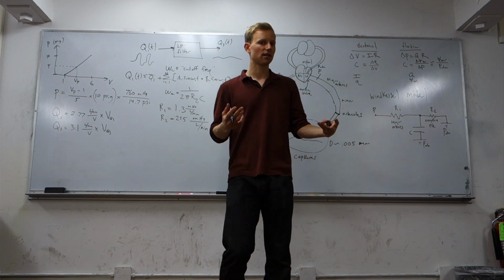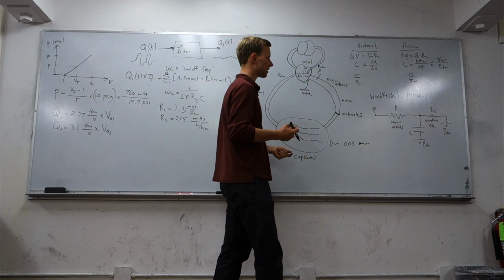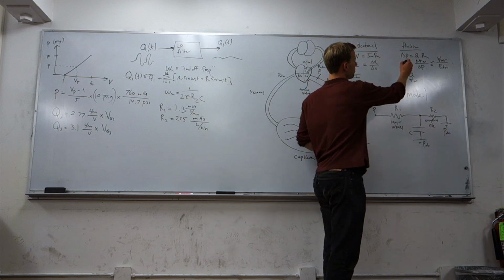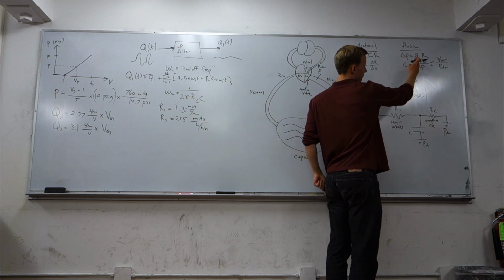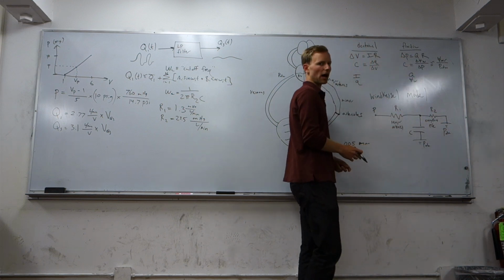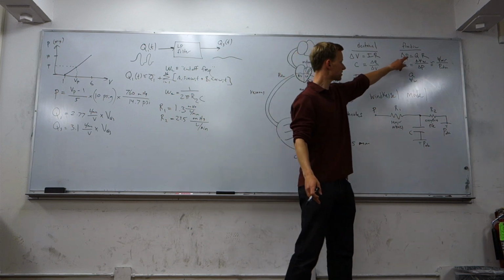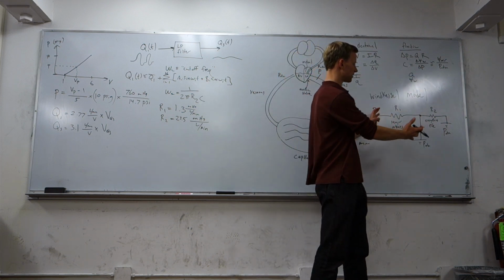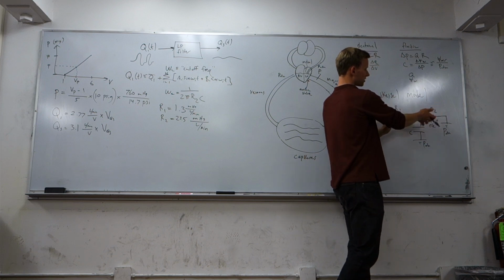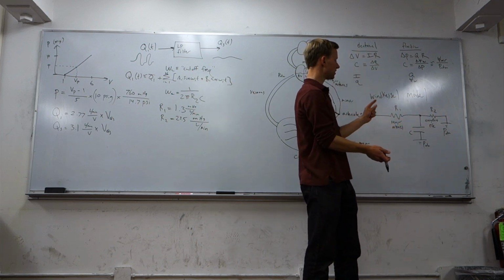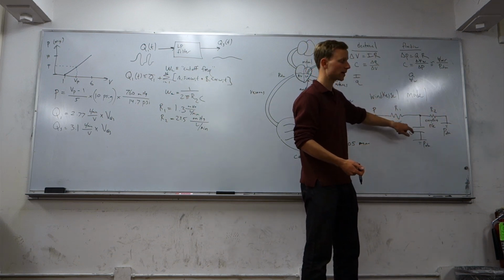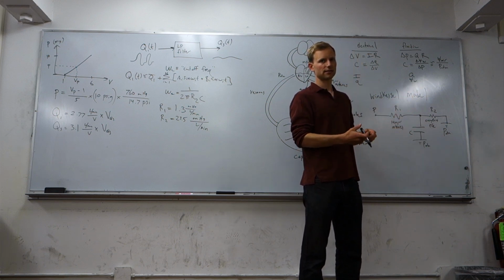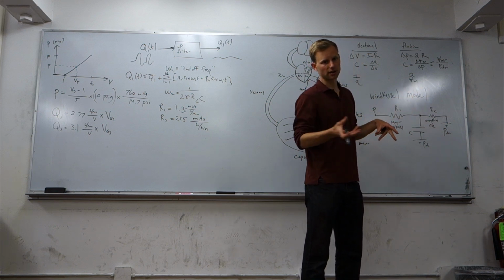So if you just take the equation for pressure drop in a pipe and you measure a delta P and you measure a flow rate, that won't help you very much because this equation doesn't hold including the capacitor. You have to take into account the total impedance of this whole element, the R's and C's. But what we could do is try to get rid of the capacitor. So we could unplug the capacitor and then run it, but that's difficult because our flow goes through the capacitor.